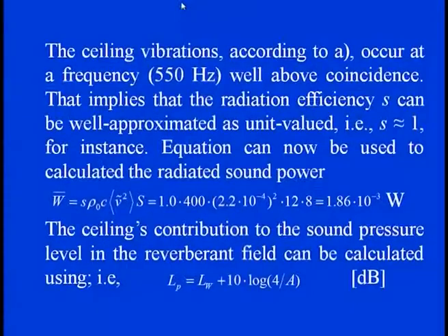So this much sound power is being transmitted and generated along the machine itself by transmission of this much vibration at the 550 Hertz exciting frequency. And the ceiling's contribution to the sound pressure level in this reverberant field can be easily calculated, with the sound level at that point equal to LW plus 10 log of 4 divided by A.